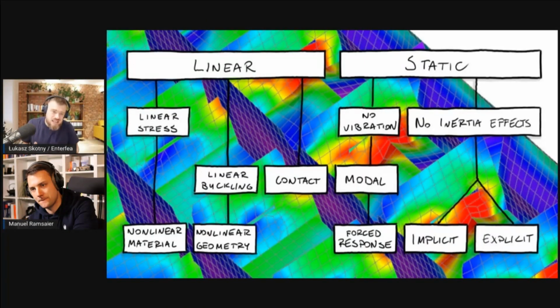So it will basically do the same thing what nonlinear solver in static would do. There will be increments, iterations, and convergence checks that in the end would allow you to iterate through the problem on the time increment you as the user defined.